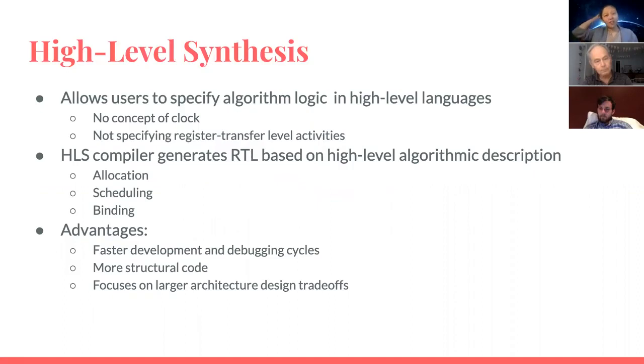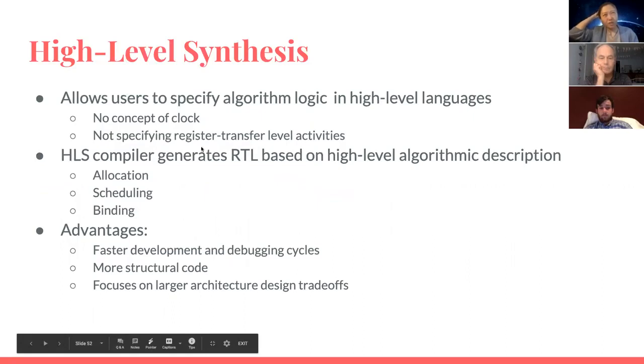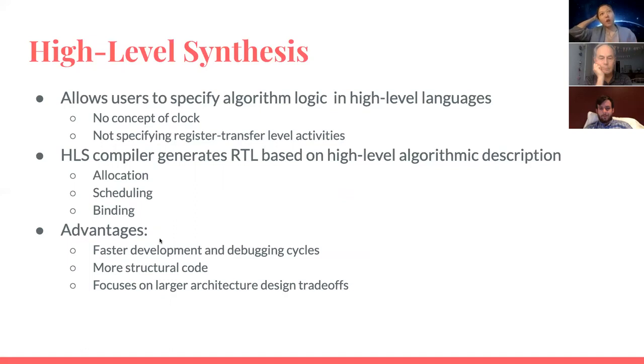So what high-level synthesis does is that it's another abstraction for developing hardware. The reason why developing hardware is very hard and time-consuming is that people need to specify register transfer level operations for each of the signals, and a lot of complicated control has not been abstracted away. Once you specify one signal wrong in your Verilog, you need to look into the waveform, and it's very hard to find if one signal is wrong with the RTL level abstraction.